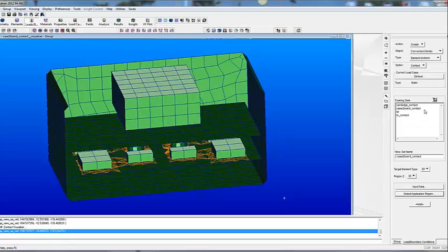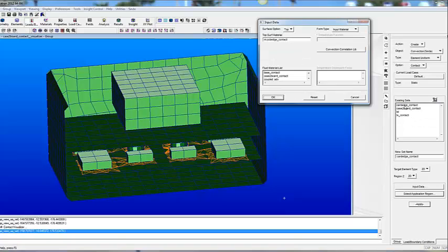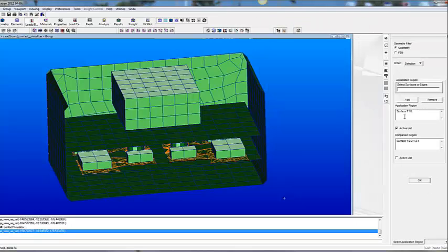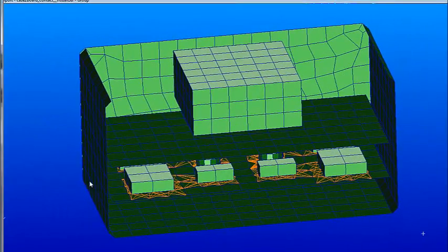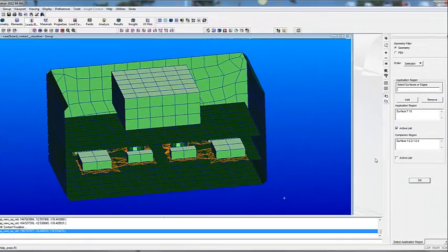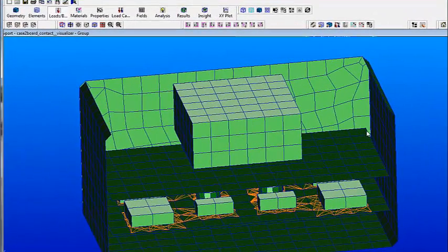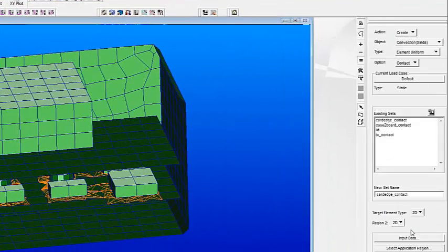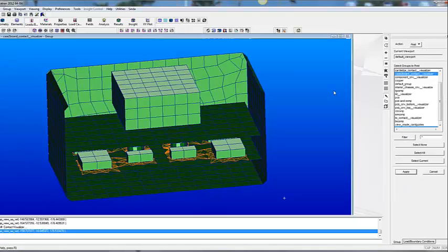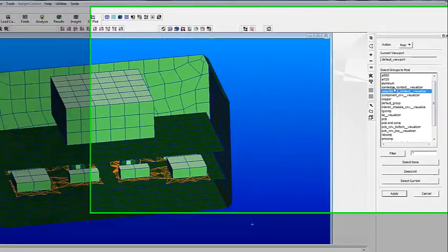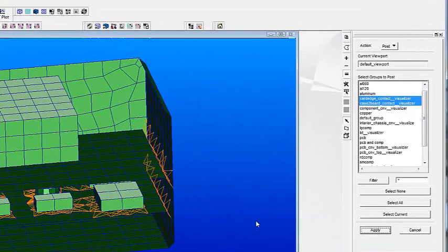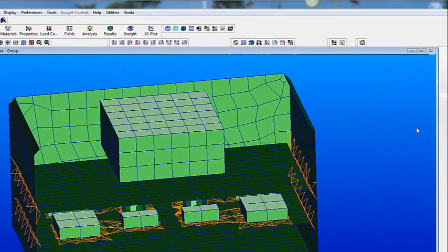And you can see we also have the PC board card guide contacts, and here these are edges of the surface, for example the edge of these two surfaces, and then surface 7 and 10 are those two walls there. So we're looking at the 4 edges of these different surfaces, and the PC boards, it's an edge to a surface sort of contact. So again, those are very easy to put in, and then they're automatically computed at runtime, and we can post-process and also add those to our model if we want to see them. So this concludes the model of an electronic box.